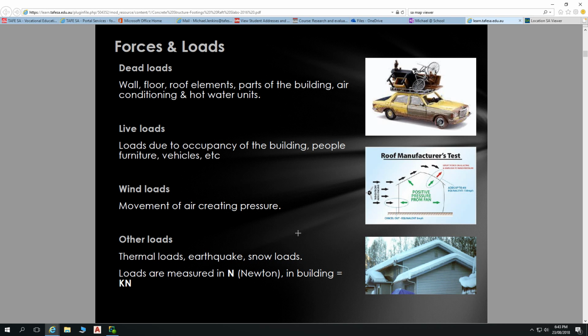It's an incredibly expensive thing to go repairing and to rectify and reinstate. So your dead loads and live loads, within this room here, we don't have a huge amount of dead load. Dead loads are anything that's sort of built into the building that we will expect that load is always going to be there. So yeah, really in this building, maybe these pin-up boards, you'd say that's a dead load. There's not a lot of load in that, but beyond that, not a great deal. All of these desks are transportable. That relates to the occupancy of the building, how the building is going to be used.